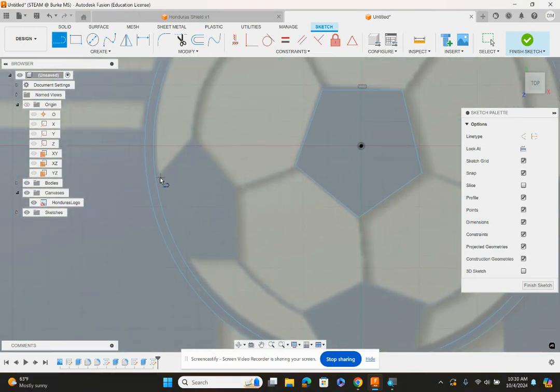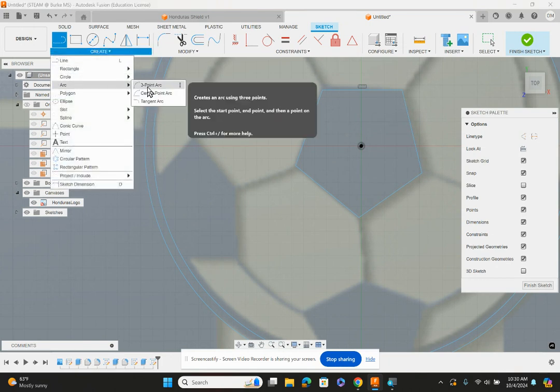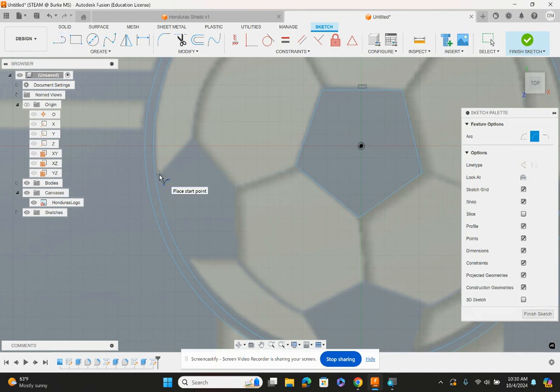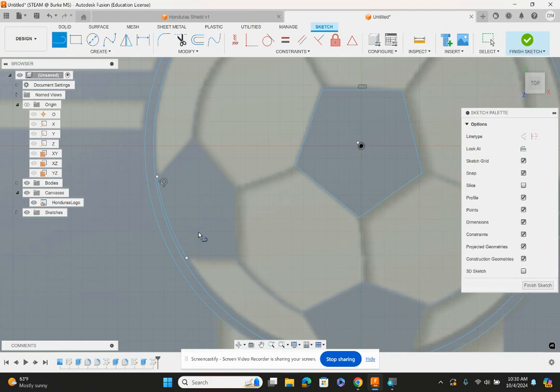The features are closed. It looks like I'm going to need an arc on this one. So I'm going to need two tools to make this one. I'm going to need a 3-point arc, because this is an arc from about here to here. There is an arc. I'm just going to apply it there, and then I'm going to use my line tool, and I'm going to go ahead and start from where I ended here, and then up here, then this way, and as always, remember to end it so that way it's closed. I'm not sure about this. Let me just check. Is this closed? It is closed. All right.